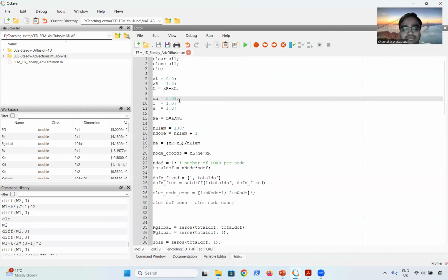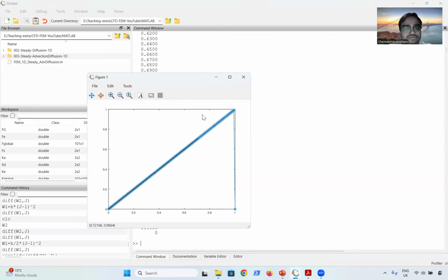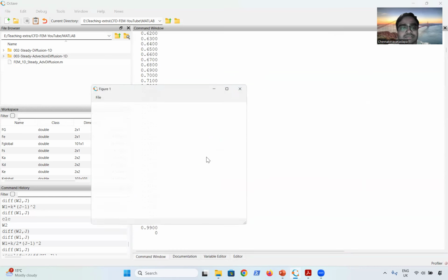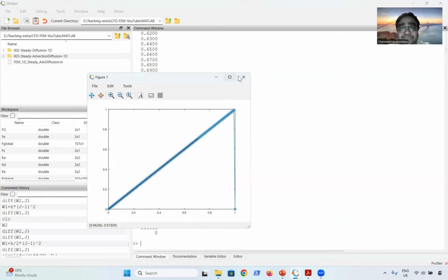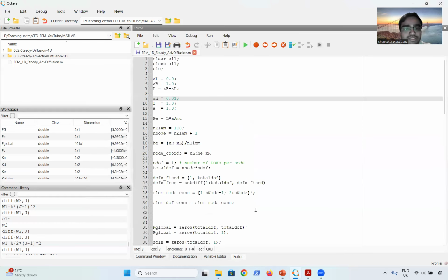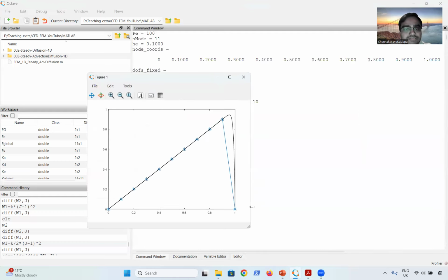And if we reduce the diffusion further, we need an even finer mesh, but using the stabilization formulation, we get no oscillations. Let's reduce the number of elements and see. As you can notice, this optimal stabilization parameter gives results with more accuracy.